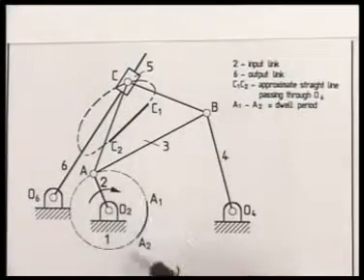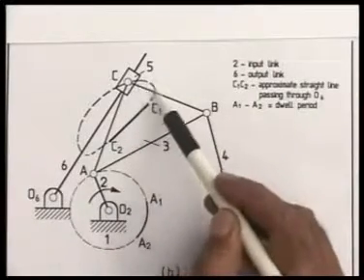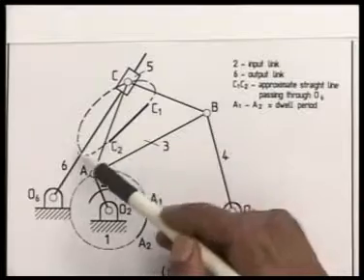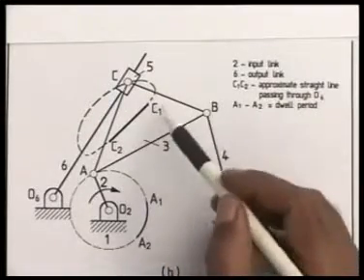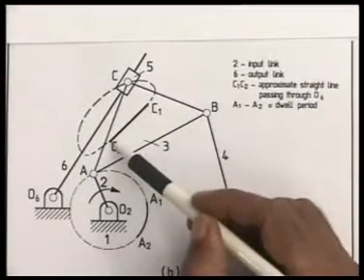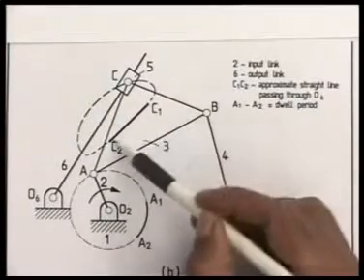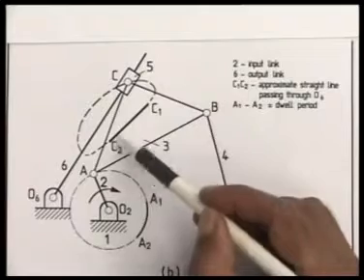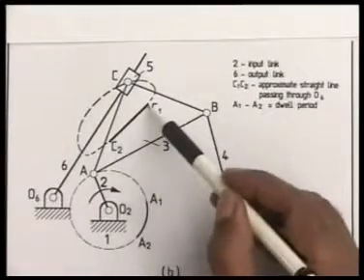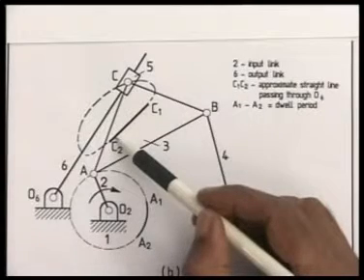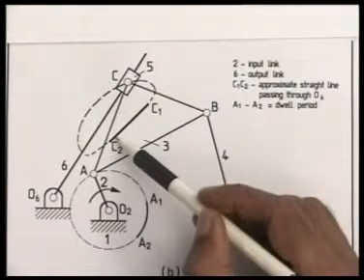As this crank rocker moves, the coupler point generates this particular coupler curve. As we notice, this portion of the coupler curve from C1 to C2 can be represented fairly by a straight line, and this will be utilized to design a 6-link dwell mechanism.